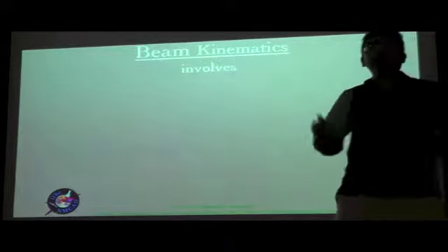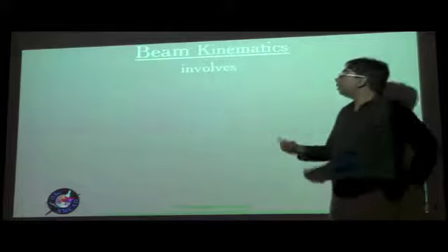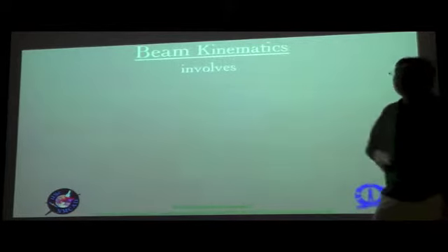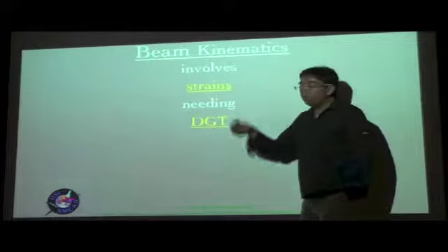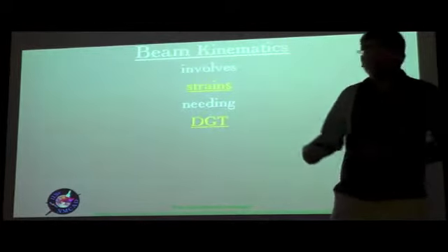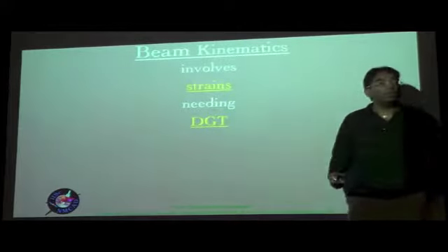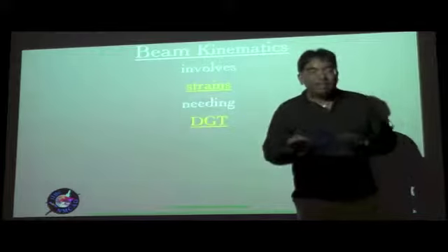And in the case of dynamics, instead of strain, you have velocities and angular velocities, etc. Okay, so it basically needs to bring in that relationship. So it first of all requires expressions for the 3D strains, which in turn need the so-called deformation gradient tensor. So if we want to derive the strain in a rigorous manner, we need a concept called the deformation gradient tensor expressed in a mixed basis.